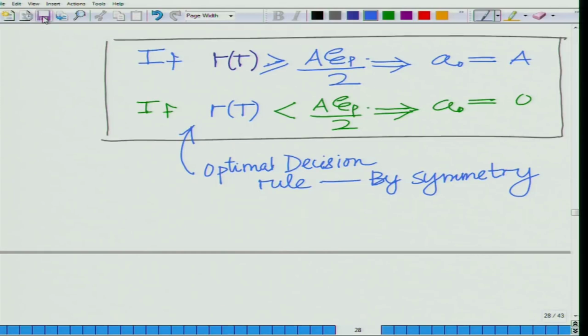All right. So, what we have seen so far is that we have started looking at different digital modulation schemes, that is amplitude shift keying, in which the different waveforms are shifted in terms of amplitude. One of them has an amplitude A, the other has an amplitude 0. We have seen what amplitude level keeps the energy per bit constant at E_b.